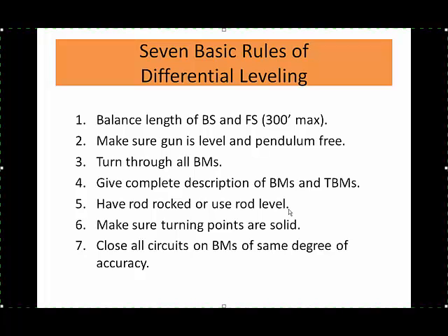If you are doing first order leveling, it would not make sense to start from a first order benchmark whose elevation is known to a much higher quality than a third order benchmark and then turn around and end your circuit on a third order benchmark. If you start on first, you need to end on first. If you start on third, you should end on third. It is possible to start on third and end on second, but there is not much gain in doing so. So make sure that you are aware of the error inherent in your benchmark.